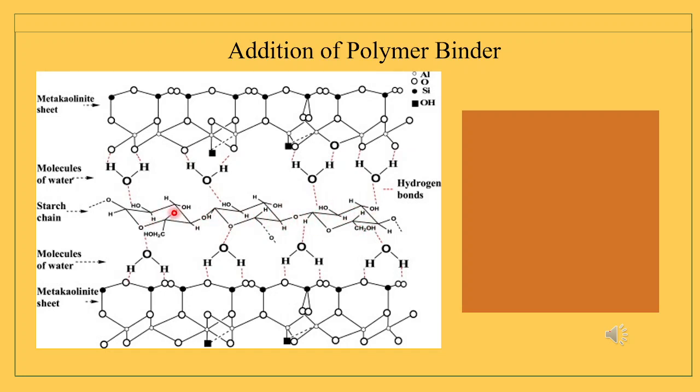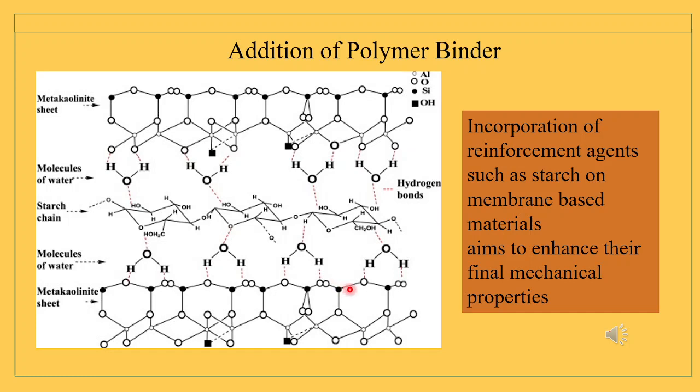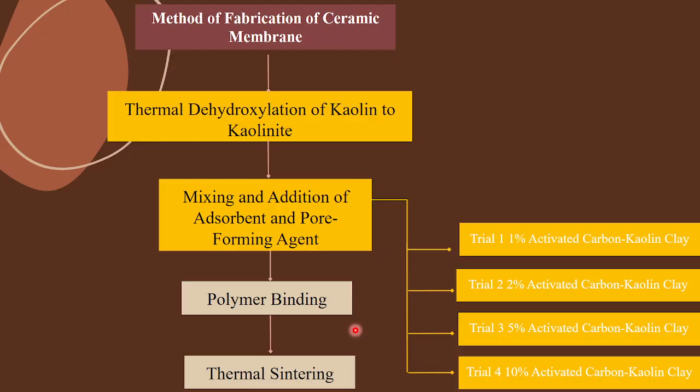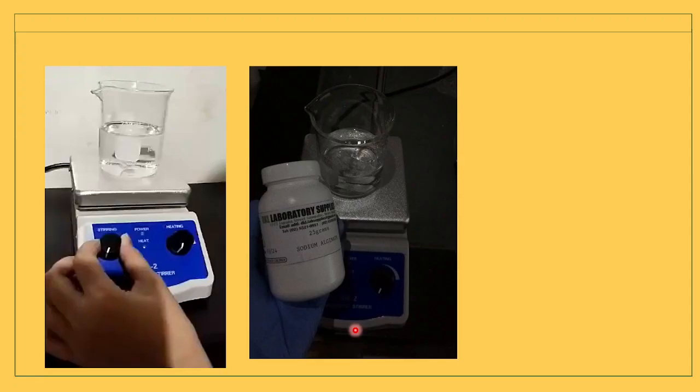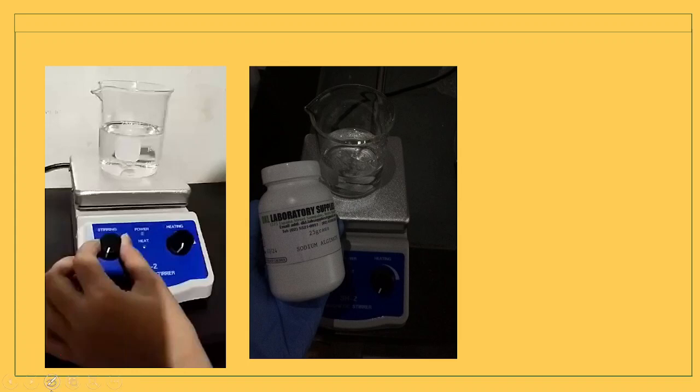Hence, incorporating starch in the hybrid improves the strength, hydrostatic stability, and proton conductivity of the base substance, which is clay. About 5 grams of sodium alginate powder in a suspension was added to increase the bonding strength of the starch clay mixture.